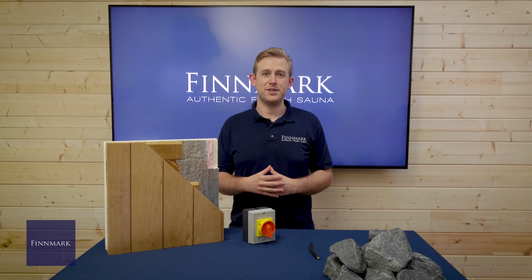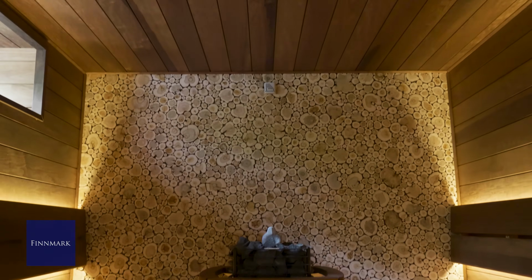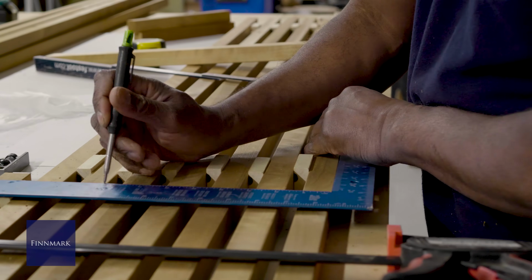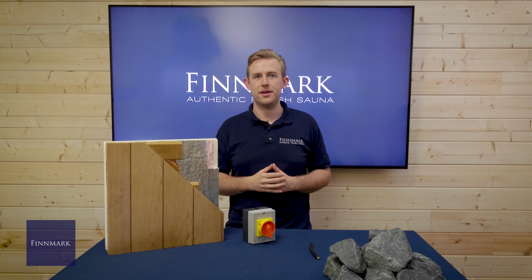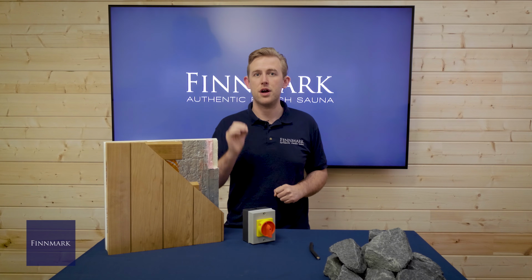There are a wide array of options for benching within a sauna, from your standard upper and lower bench on one side of the room to L-shape and U-shape bench systems, opposing bench systems with raised floors, or totally custom body form lounges. One of our pet hates though, and a cardinal sin for sauna design, is the lower bench only sauna. From time to time we see saunas specified or designed with a lower bench only, but we at Finnmark emphatically insist against this design practice.